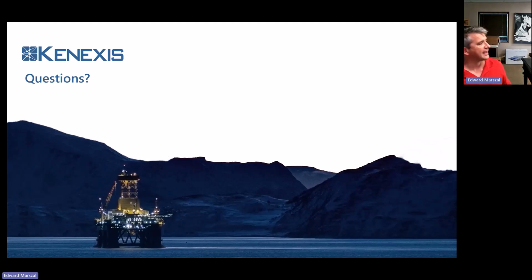So I kind of got off on a little bit of a tangent there, but no. While any fault propagation modeling tool will allow you to model systematic human failures, I strongly encourage you, in full conformance with the IEC 61511 standard, not to model systematic human failures when you're doing your SIL verification calculations.